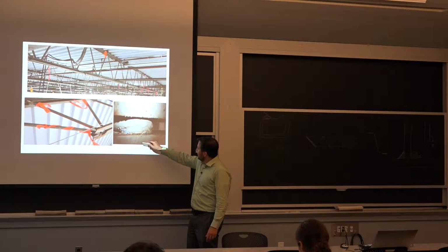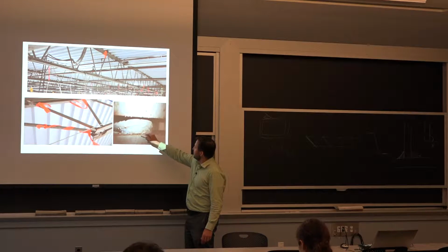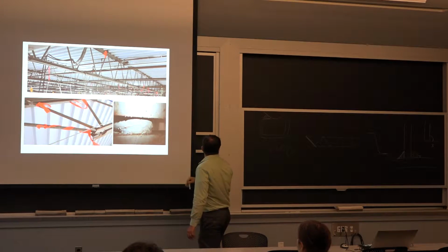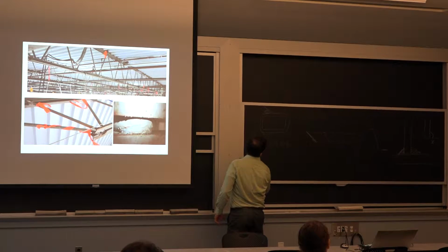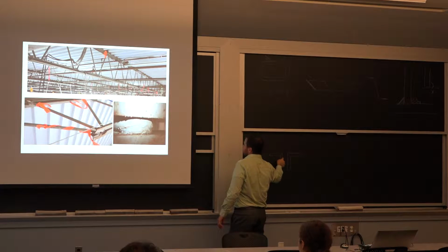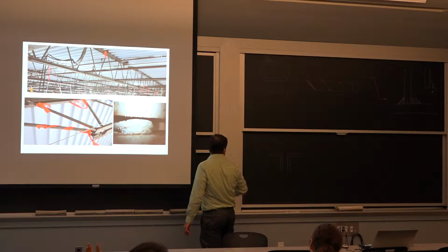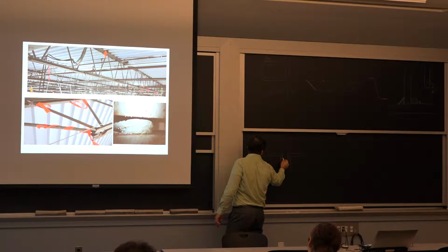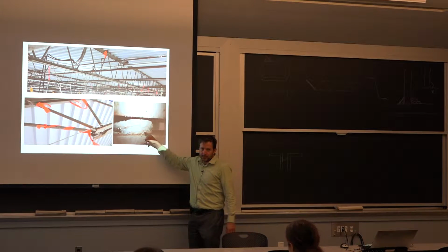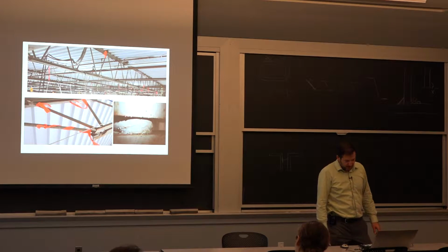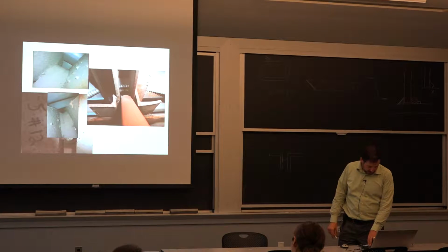Here you see physically, just looking under the joist, the separation. So I have that angle, and I have a solid bar that fits in it, just like this, and they started welding it, but they did not get the fusion on this side because you see the gap right there. So it's the most unfortunate aspect to this.